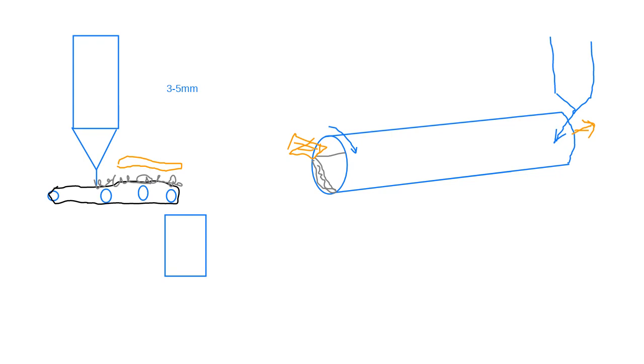But anyway, the radiation of this hot gas will also radiate onto the walls of the tube of this rotary kiln, and the walls get hot, and then any particle that impinges against this wall, as the particle moves along the wall, because the wall gets heated by the hot gas, it also gets heated, and as it rolls down, it has the opportunity to evaporate the water. So they work quite well.